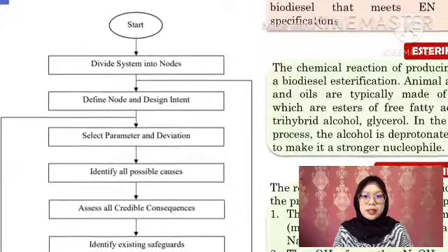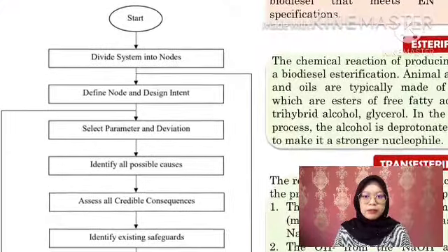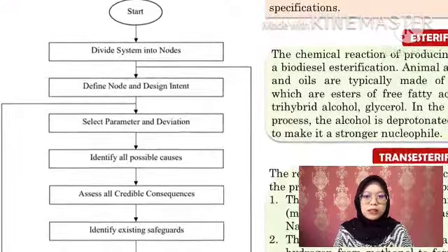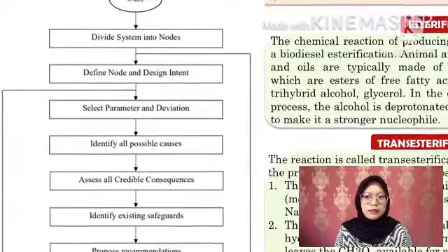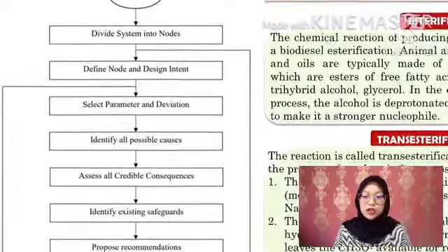So the existing and newly organized jobs have been divided into valid units and the HAZOP protocol is followed. The HAZOP methodology is given as shown in the poster. The process system is designed and the potential for deviations is taken into account. There is awareness of any possible cause of deviation. Established safeguards and protection mechanisms are identified and their ability to resolve discrepancies is evaluated.